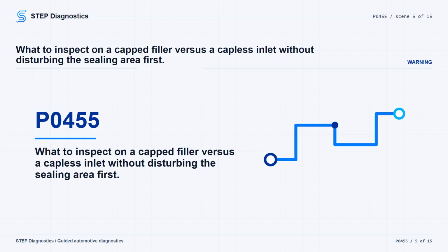Use the supplemental fueling adapter 5 times to help clear debris from the seal, then repeat the check. If a concern is found, repair it as needed and verify the repair with the leak verification pressure test. If there is no concern at the filler area, continue to the next inspection.